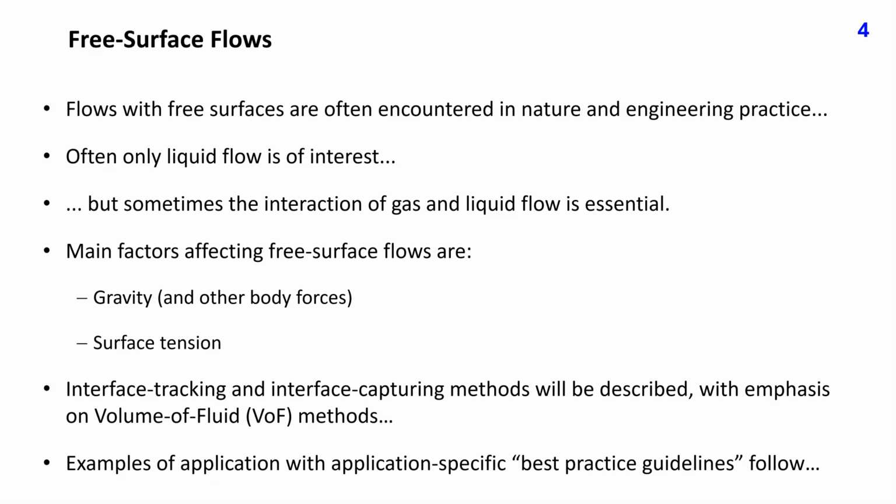In internal flows with fluids of constant density, gravity effects are usually hidden in the pressure term, that is, the solution does not depend on the orientation of the solution domain. See section 1.4 in the book. With free surface flows, gravity and pressure terms need to be separated because of a different variation of hydrostatic pressure within gas and liquid. We shall describe the basis of interface tracking and interface capturing methods with emphasis on volume of fluid methods. Several examples of application with application-specific best practice guidelines will be presented.